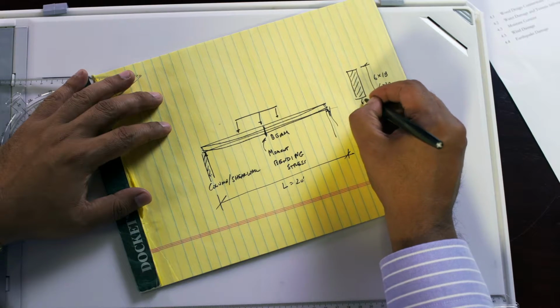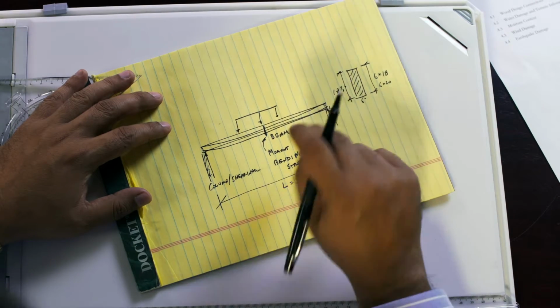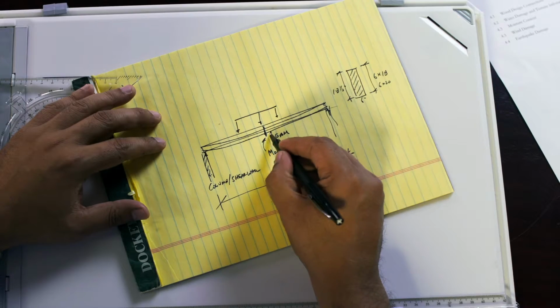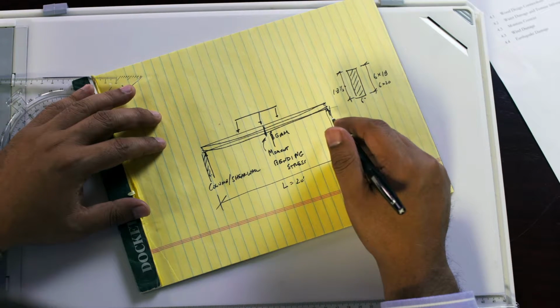And so a 6 by 20 is 6 inches wide by 18.5 inches deep. A lot of architects have an issue with that because that's too tall, it's too thick. They want to have a thinner span. So either I have to go with a different material, or I have to put in some column load in order to reduce that span length so that I can put in a smaller floor beam.